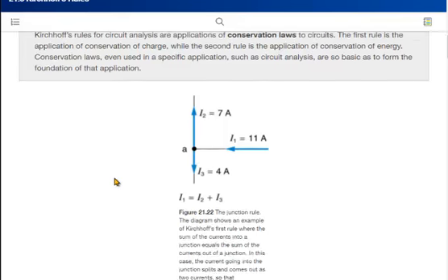Okay. The other one, here's the second rule, is just as easy. It actually looks a little bit too complicated for me here. So here, for example, we have a battery of 18 volts, and now these 18 volts of the battery here are distributed in this series circuit. So here, this one here takes 1 volt, then this one over here takes 12 volts. Just calculate 17 minus 5 here is 12.